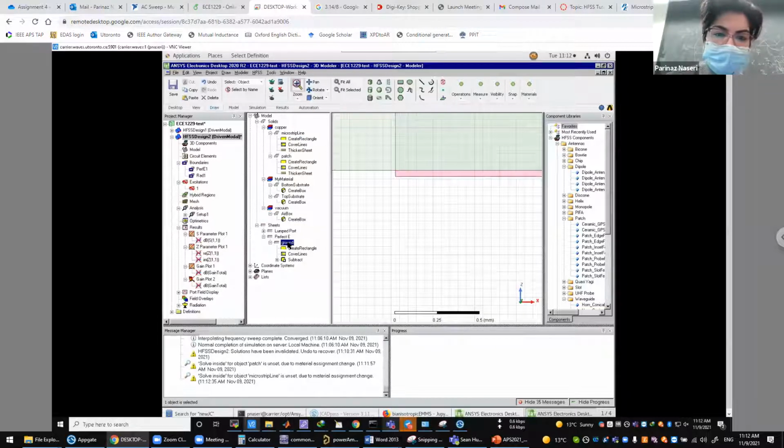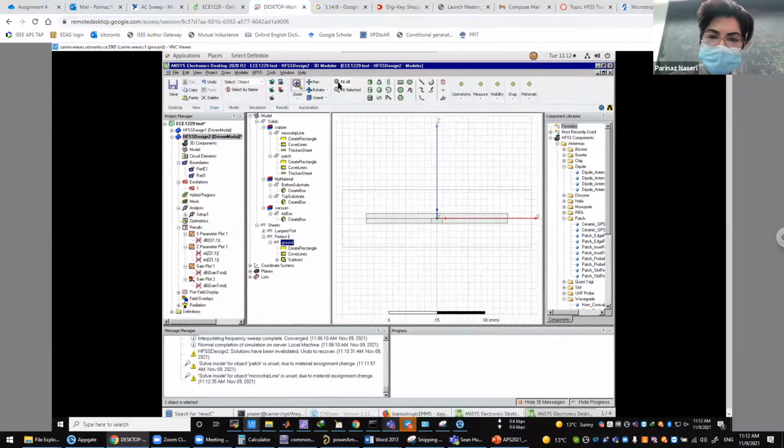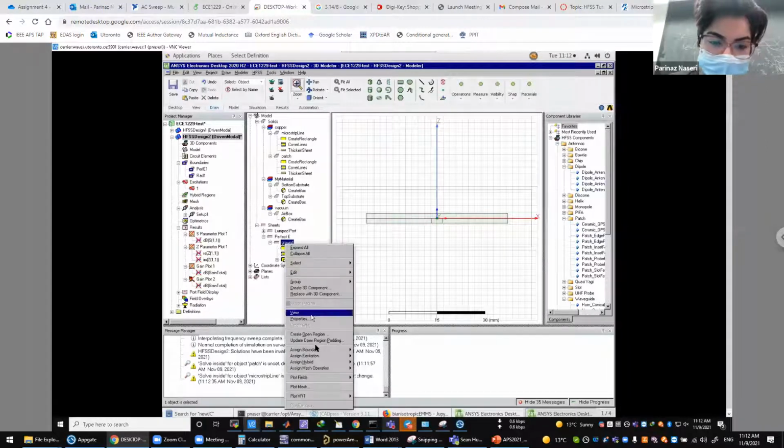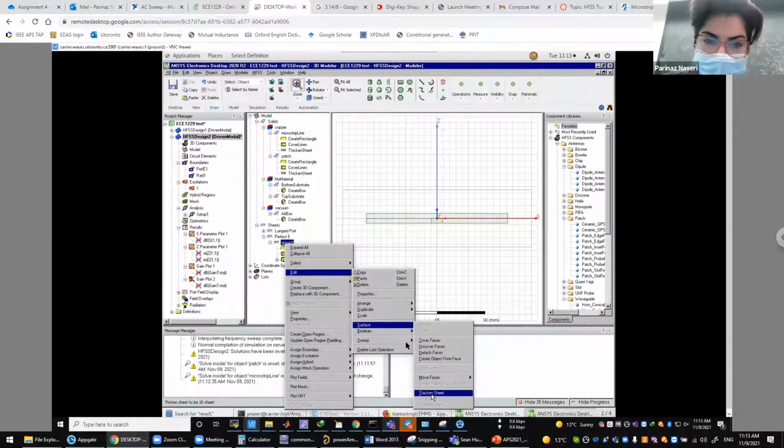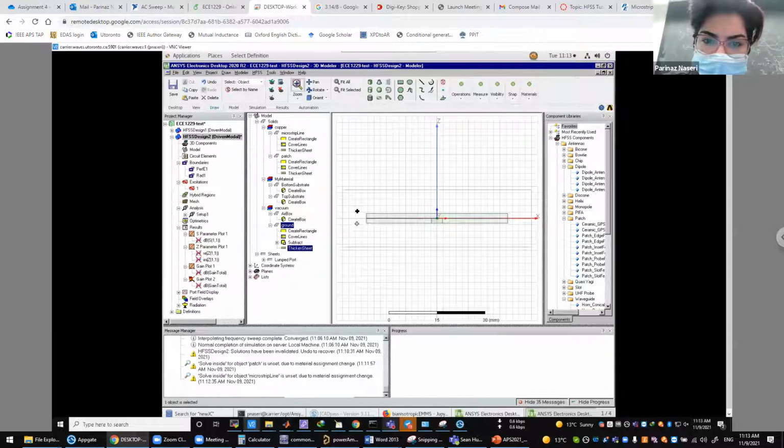So now the ground is a little bit trickier because as you add thickness to it, whenever you have a layer in the middle, you have to actually separate the dielectrics, right? So I'm going to add thickness to it, but if you want to be really thorough, you have to consider this thickness in the distancing between the dielectrics. I'll show you how. So surface, thicken the sheet, goes here.